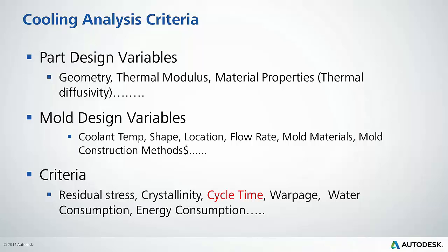So thermal diffusivity is an interesting property because it kind of combines a lot of the key thermal properties, right? It's thermal conductivity, calculated thermal conductivity over density and specific heat. So we kind of have a rate, thermal conductivity or speed rate of how fast we're flowing, and then this density and resistance to heat transfer, right? How much energy, specific heat, how much energy do I need to put into this material to raise or lower it in temperature? So the